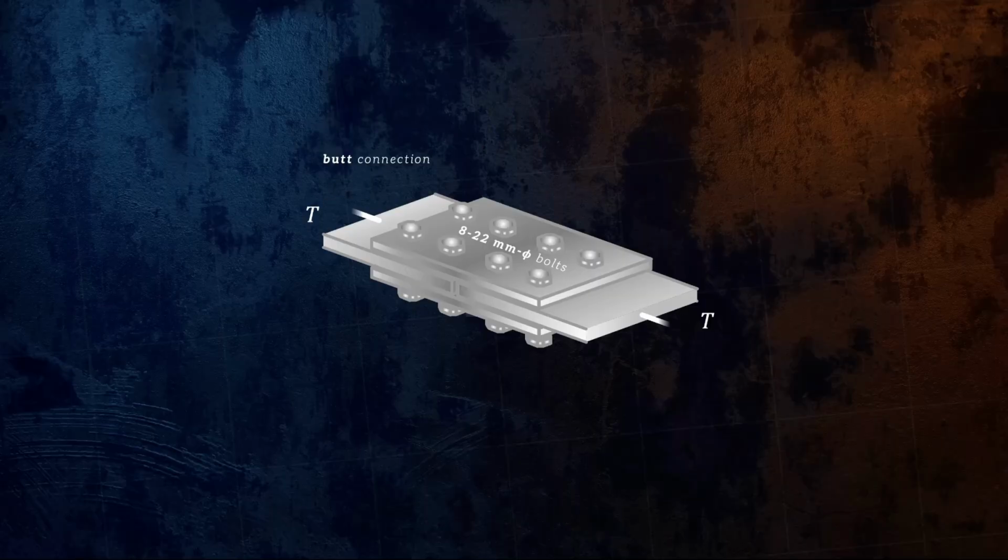Now, we can clearly see that there are middle plates sandwiched by thinner plates at the top and bottom. These plates are held in place by 8 22 mm diameter bolts, thus giving us a butt-type connection. This connection is subjected to a tensile force T.